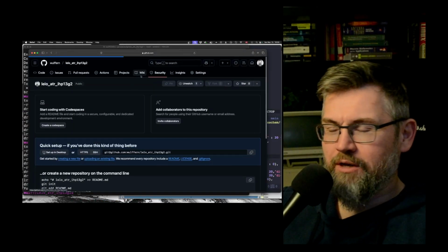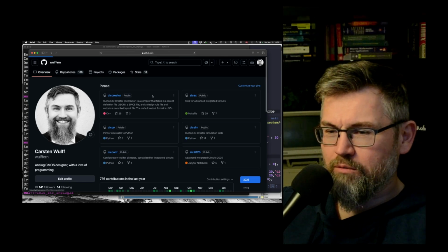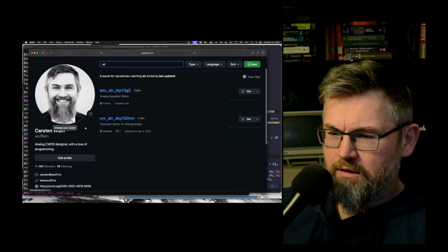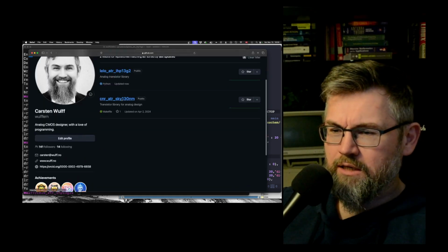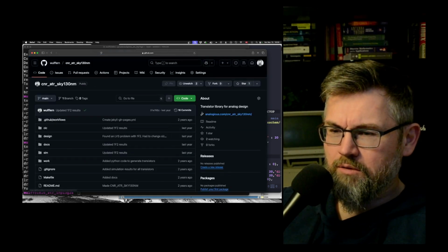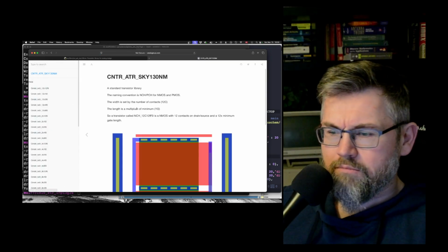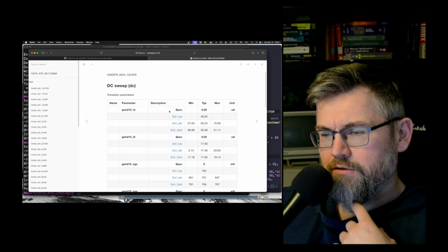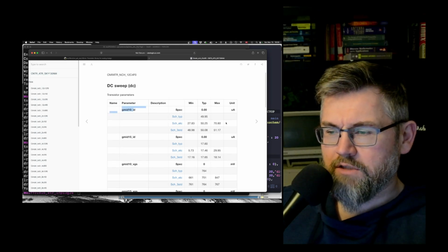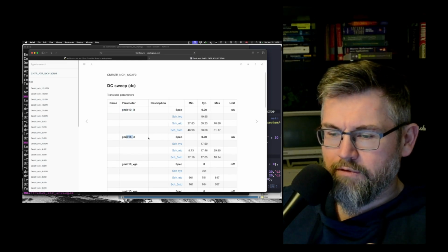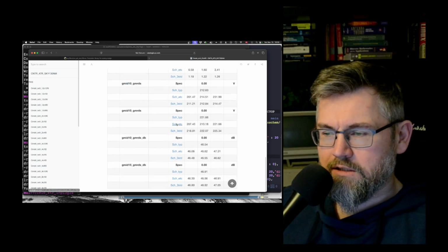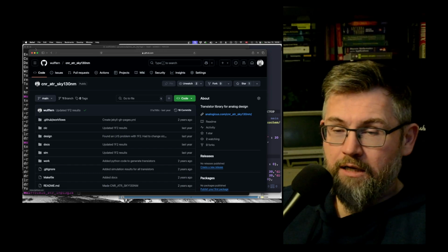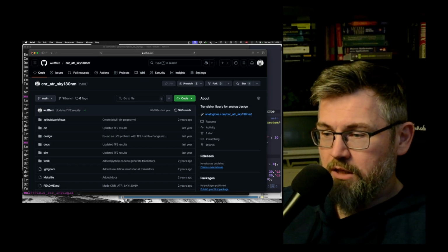Let me show you how I have it for the old library. No, actually, yeah, we have the Connor version. That's okay. So this is one of the old transistor libraries, and I do simulate everything. So I get for a GMID of 10, I know what current to put through, and for 15 and so on. So that's simulations I need to set up and run. But already the layouts there, it's possible to do that anywhere else.